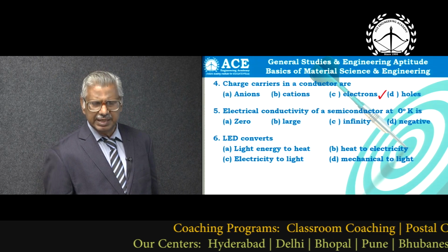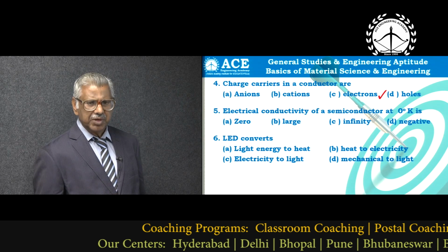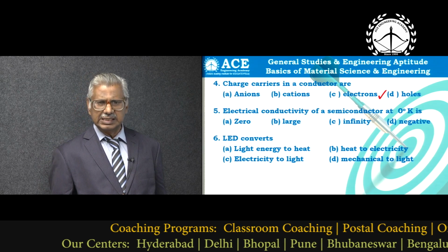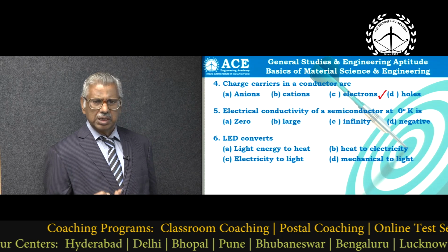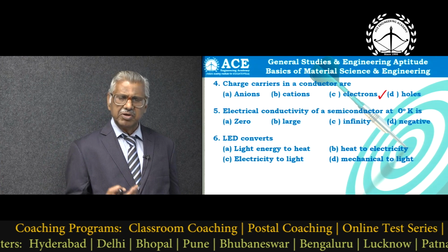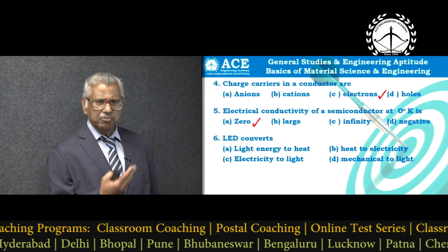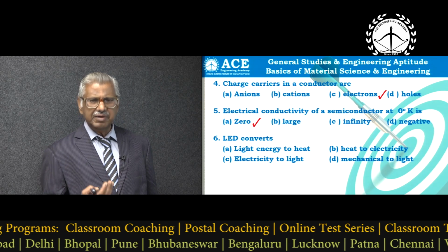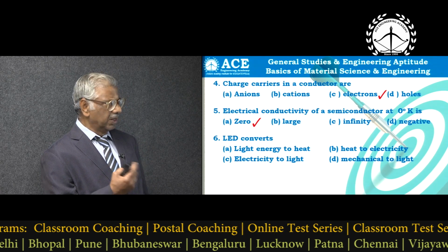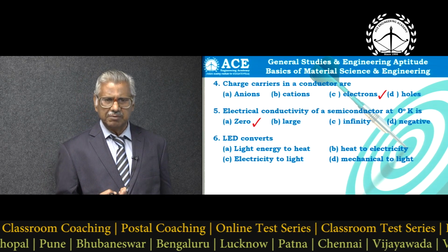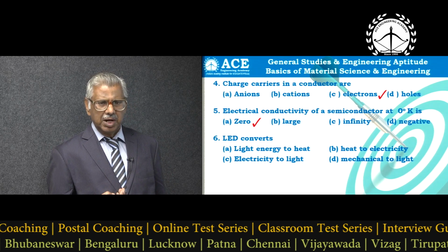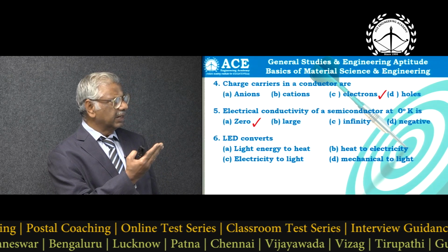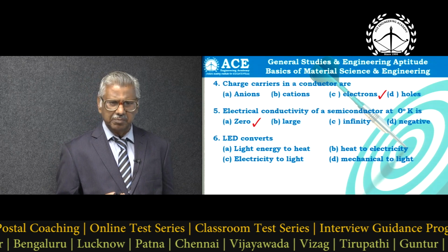The basic idea being, since we will be using our various electronic devices at different temperatures, we will have to know the variation of their parameters with respect to temperature. So if you look at the semiconductor, and if I take it all the way up to absolute 0 Kelvin, what happens? Obviously it becomes a perfect insulator, and the conductivity becomes 0 in that case.